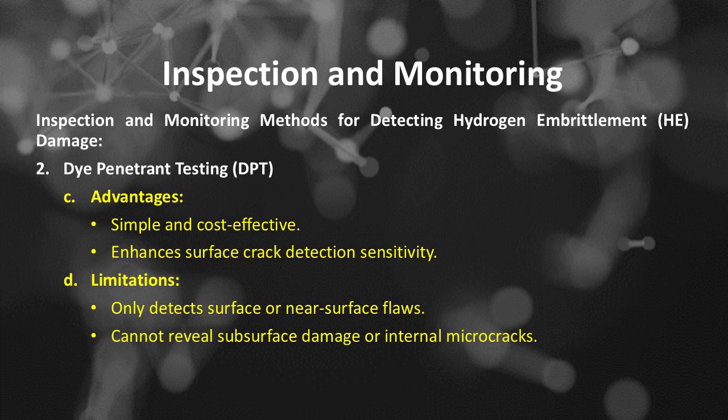Dye penetrant testing advantages include being simple and cost-effective, and enhancing surface crack detection sensitivity. Dye penetrant testing limitations include that it only detects surface or near-surface flaws, and cannot reveal subsurface damage or internal microcracks.